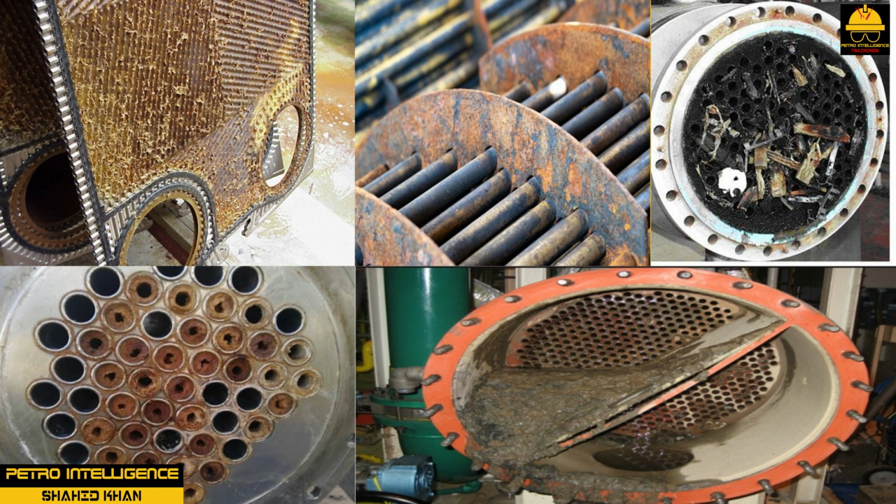An exchanger's fouling resistance depends on the type of fluid being handled, the amount and type of suspended solids in the system, the exchanger's susceptibility to thermal decomposition, and the velocity and temperature of the fluid stream. Fouling can be reduced by increasing fluid velocity and lowering the temperature. Fouling is often tracked and identified using checklists that collect tube inlet and outlet pressures, and shell inlet and outlet pressures. This data can be used to calculate the pressure differential, or delta P. Differential pressure is the difference between inlet and outlet pressures, represented as delta P.